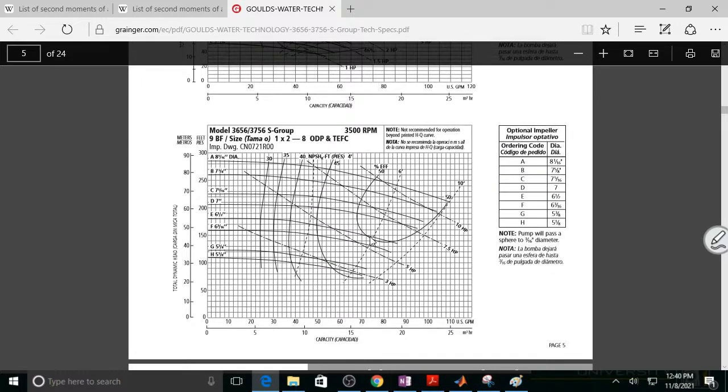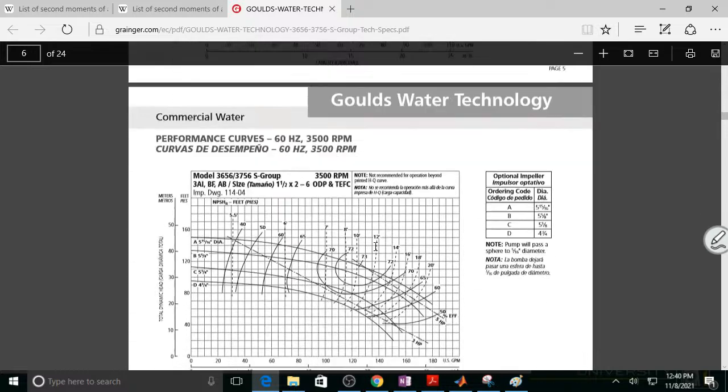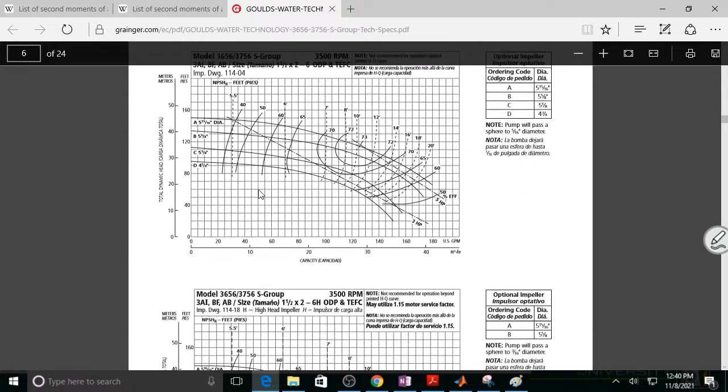And so what we'll do next time, we'll pick one of these types or groups of pumps, pull it off, copy it, put it on there, and then calculate the system curve to figure out where it actually ends up. Some of them are thin, like this one. We'll look at these, which are the efficiencies. So there's your efficiency of the different things.